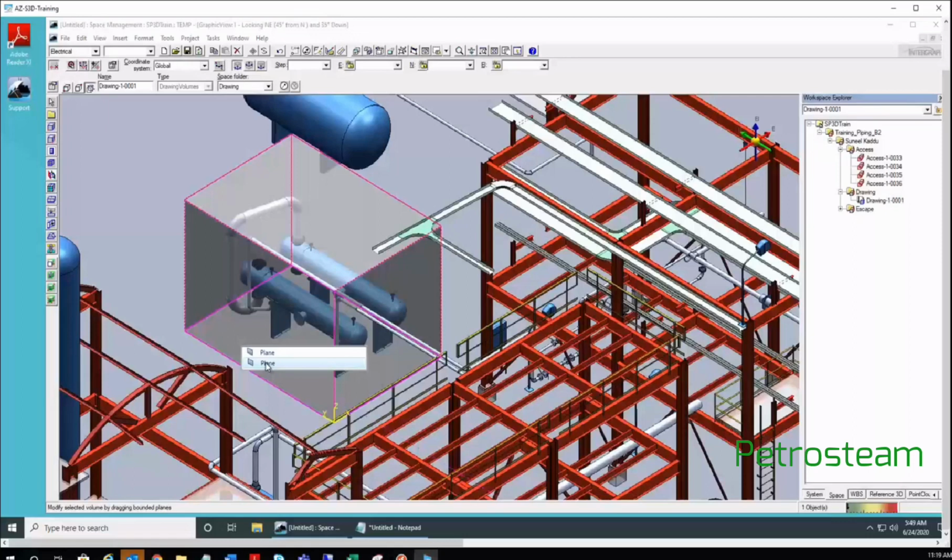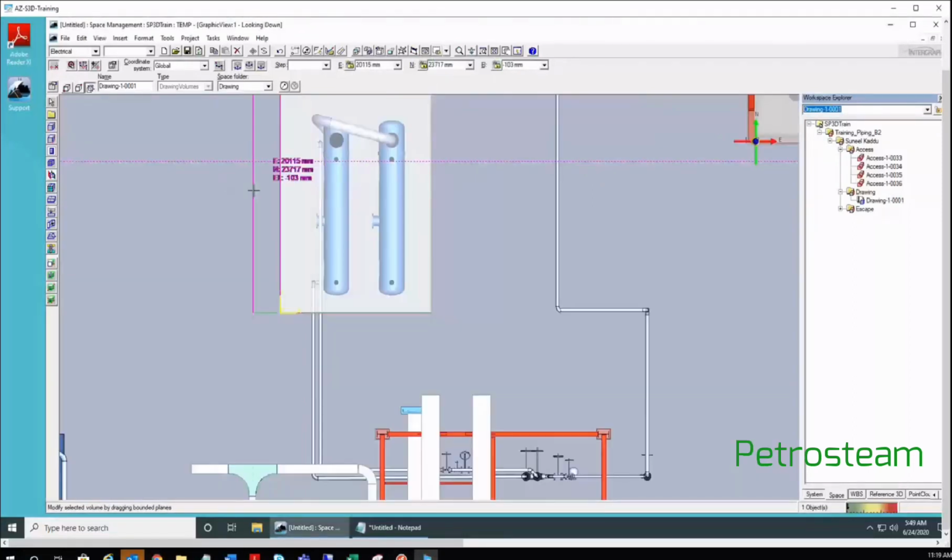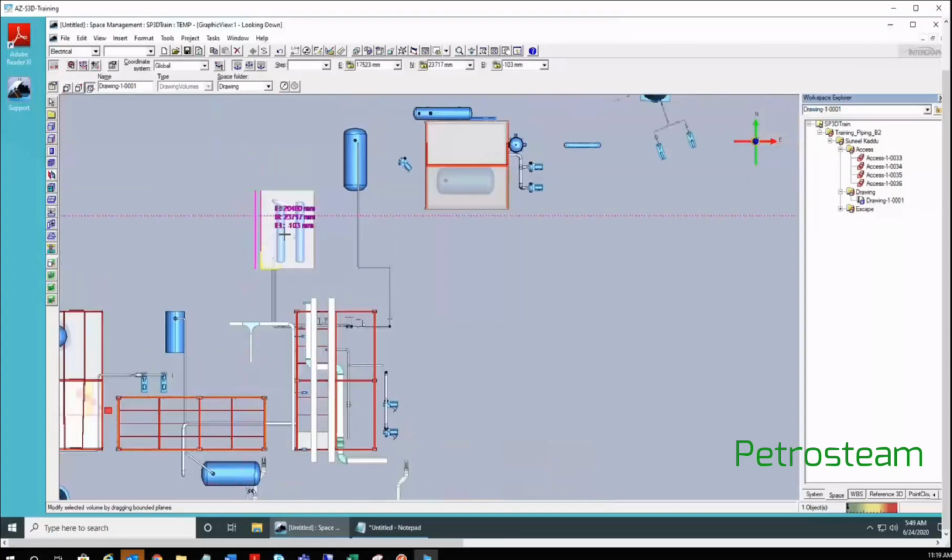If you select that plane, say west face I will select, and then you can observe in top view. Once you select west face, you can just modify it wherever you want. Even using pinpoint, you can input the value for it here. North and elevation are fixed, only plane is moving. In that case, only easting you can change now for this.